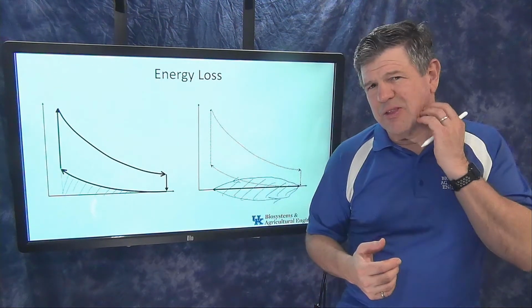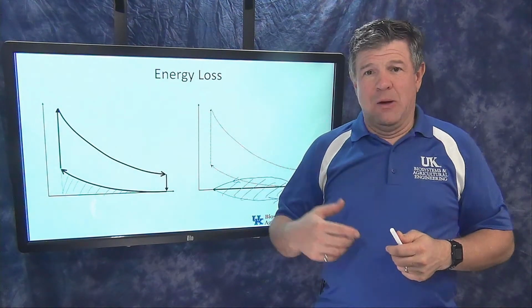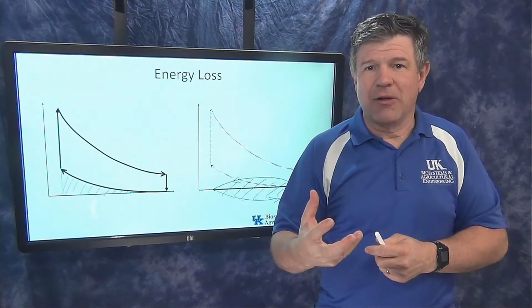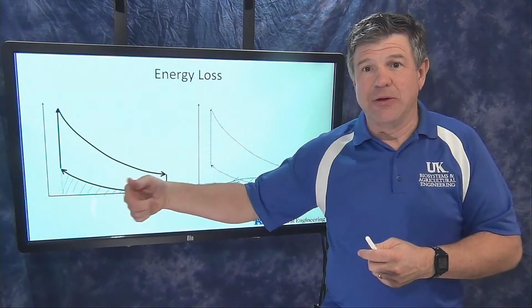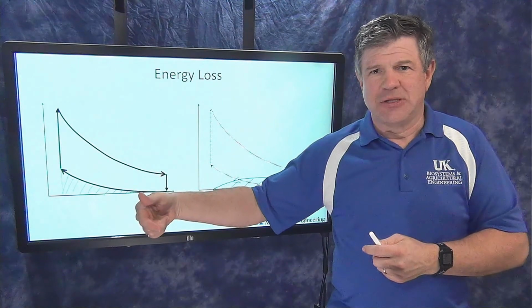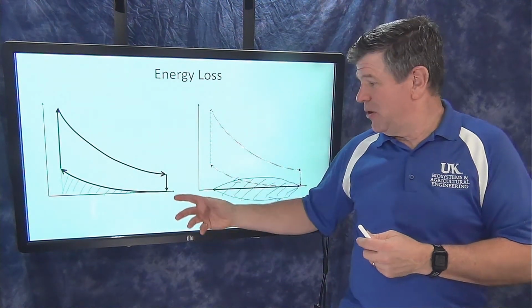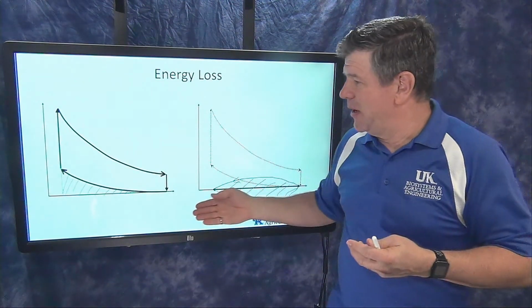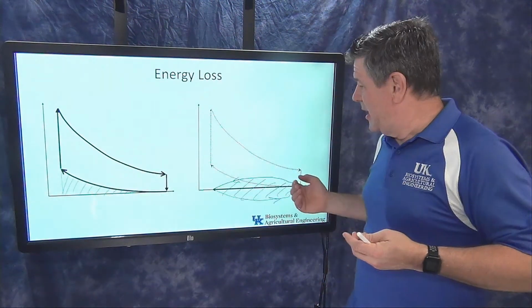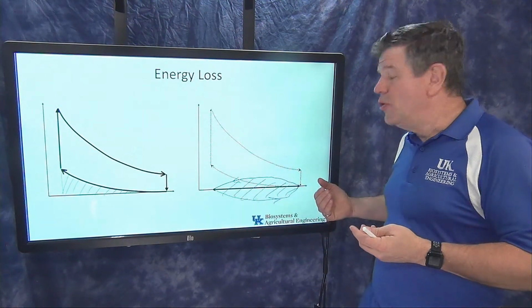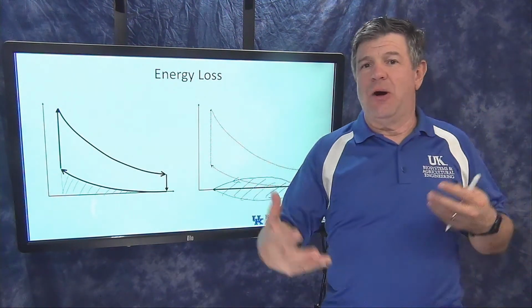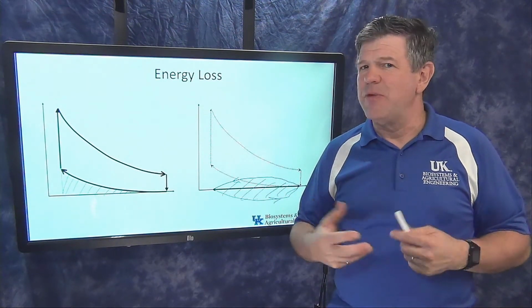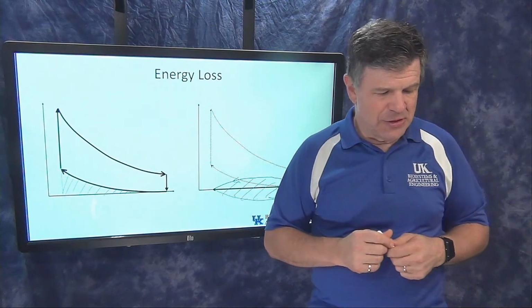And here's where we start to think about, wow, okay, so if I think about the energy that was in that fuel that went into the engine, I can't get all of that energy from the fuel going out and doing useful work on my crankshaft. Some of that energy from that fuel has to go into just keeping the dumb thing running, just keeping the system working, being able to compress the gas, being able to get the gas out, being able to pull new gases in. That all takes energy. So that's going to be kind of a parasitic thing from the fuel that goes into the engine. So those are energy losses.